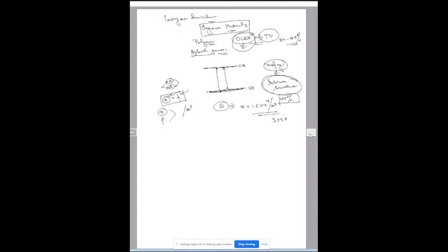because it is temperature dependent. But if we add a small amount of impurity to the semiconductor, we can change the number of electrons or holes by choosing the impurity properly. For example, in silicon, if you choose an impurity from group 5, you can create a large number of electrons as compared to holes.